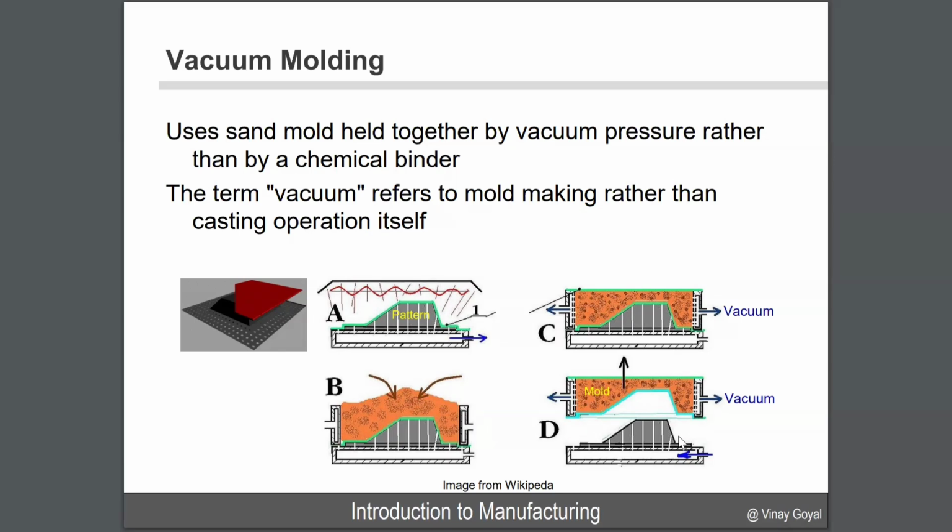Now, the benefit here with vacuum pressure is that the pressure is going to try to compress the material to then remove the voids that are internally in there. Again, this is not in the notes, but I'm explaining to you from experience. So there's a benefit there of vacuum pressure because you can try to extract those voids out of the process.